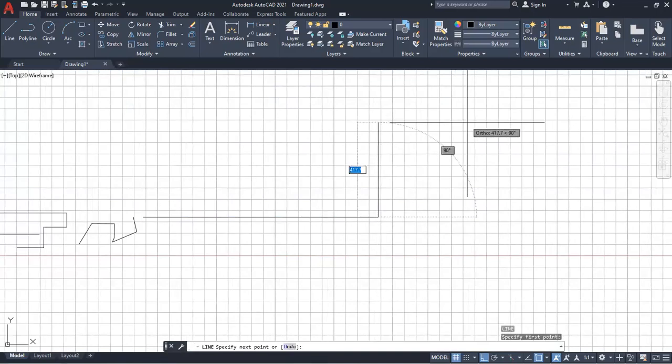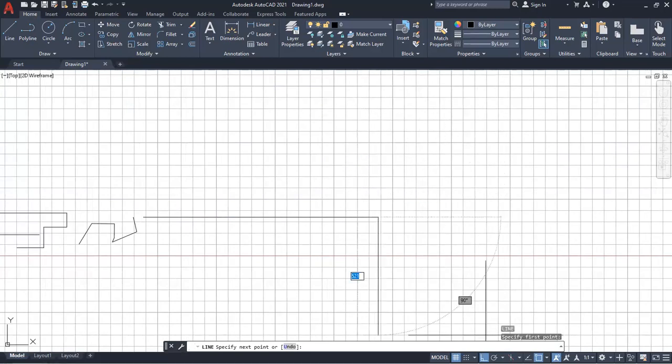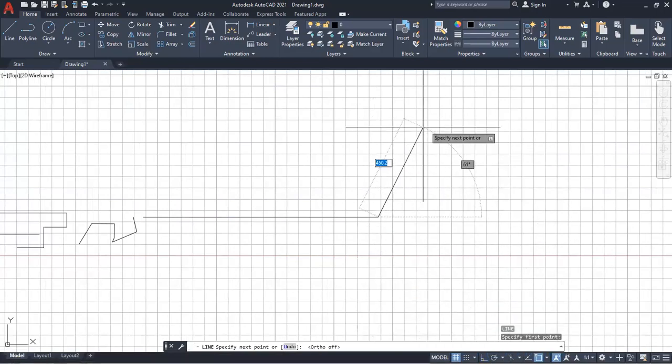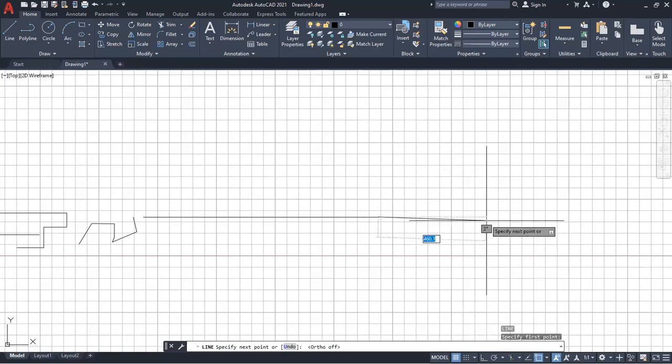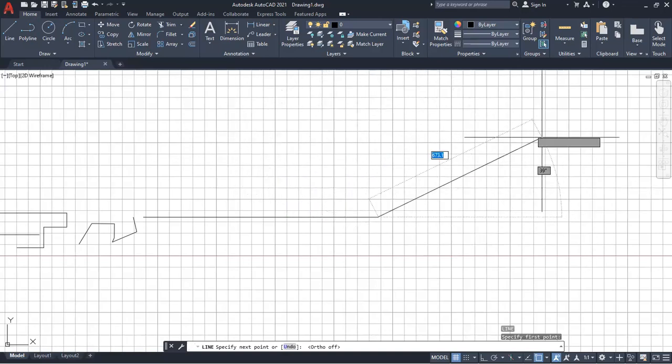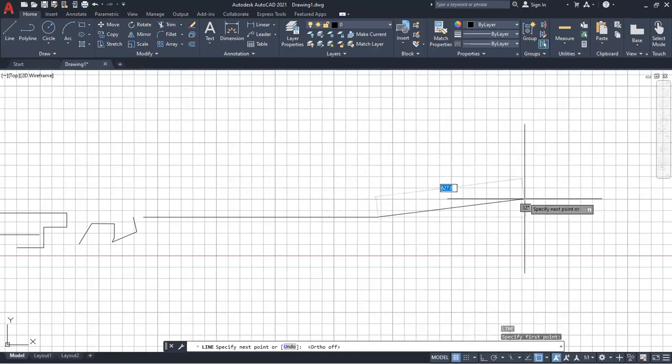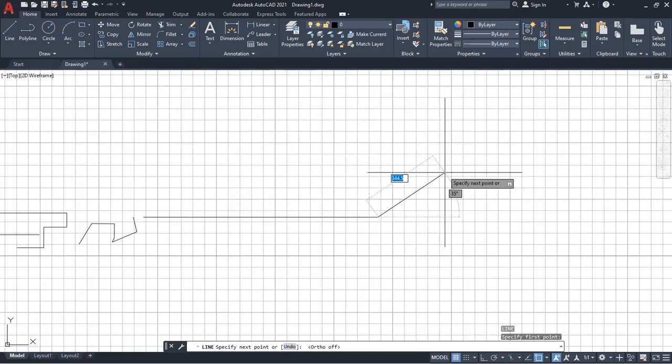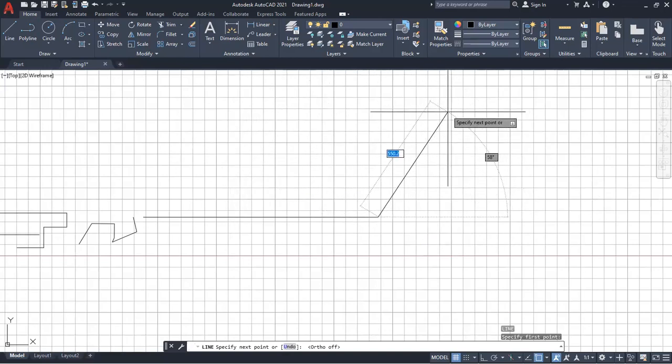The new AutoCAD feature allows you to draw a line that is straight, and you can also give it an angle. If you want to change the angle from 90 degrees, you can switch off your ortho mode, and this will let you draw at whichever angle you need. If you want to change that angle to a specific angle, you need to hit the tab button.